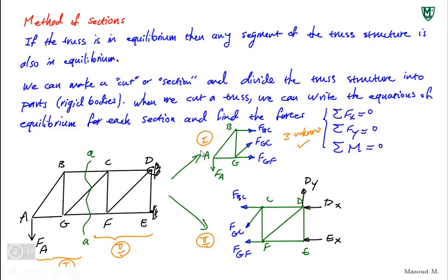Then once I make the cut, and assuming that I can't use section 1 for some reason, I can use section 2, because once I make the cut, then support reactions are known from my analysis of the whole rigid body, finding support forces and moments.